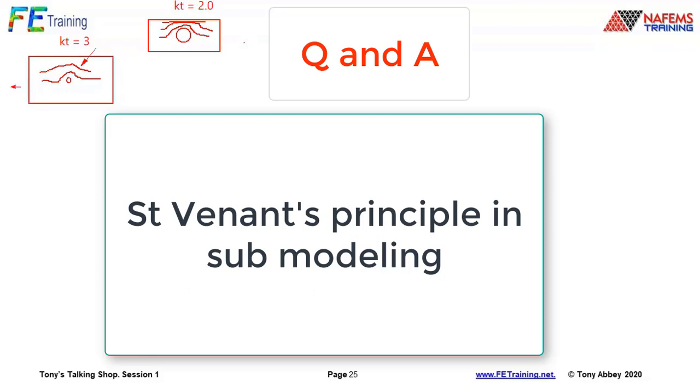So that's really what we're trying to do. For the needle there, I came up with probably about 3 diameters looked safe, looked okay. I had that kind of study where I came right into half a diameter. There, the influences were bad, and they were really wrecking the value of the results. As I spread it out, we got to that kind of critical length. If you go too far, you're not doing any harm. You're just wasting elements.